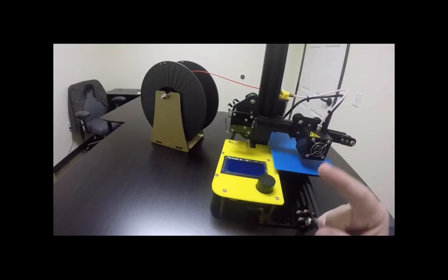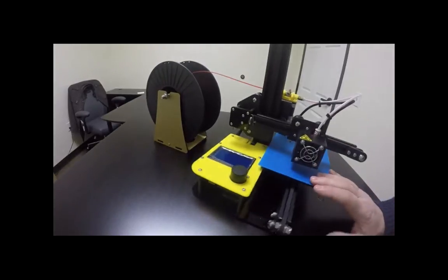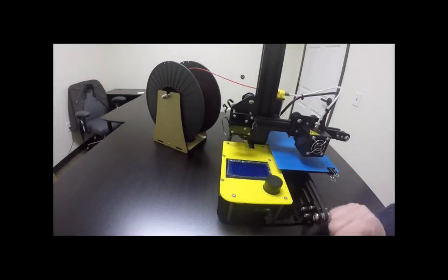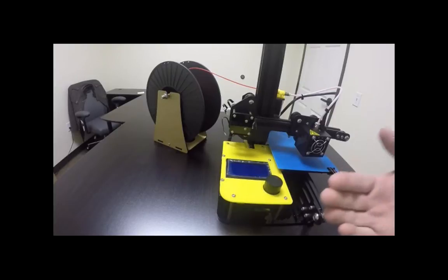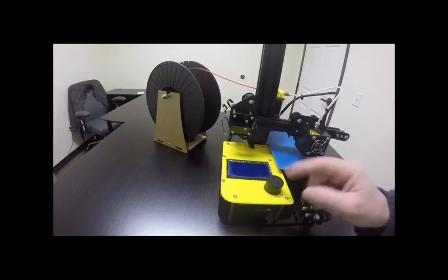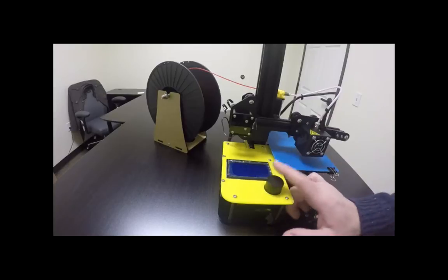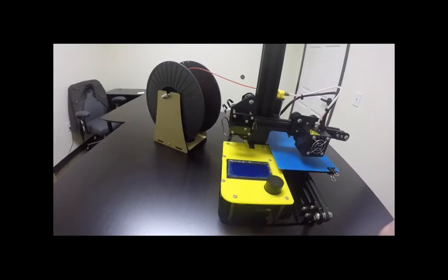So the last thing that we're going to do right before we print Squirtle is we're going to test the build plate and make sure the build plate's level. So to do that, we'll tap the button, and then go to prepare. And then normally you'd want to hit preheat PLA to heat it up. But since we've already done that, it's already heated up. We don't have to worry about that step. So just go to auto home and tap the button. And then that's going to move the X, Y, and Z to 0. And then when it stops moving, then tap the button again and go back to prepare. And then where it says disable steppers, tap that button to disable the steppers.